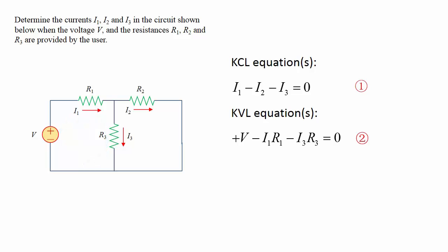And then I'm going to write the KVL equation for this big loop right here. Again, I have a voltage increase from the power source, and then the current flows through 2 resistors, R1 and R2, and I have the 2 voltage drops determined from Ohm's law respectively, I1 R1 and I2 R2. And that's my third KVL equation.